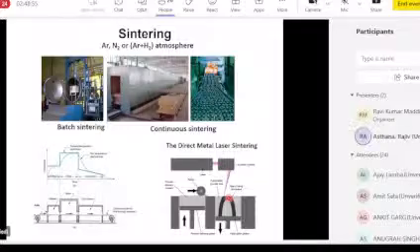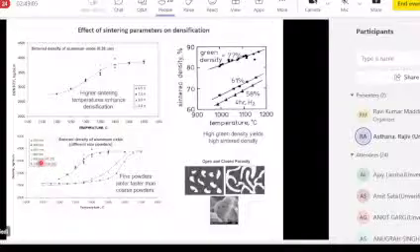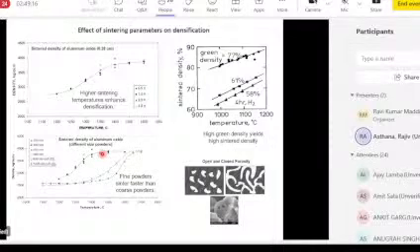Or as a function of sintering temperatures. Typically, higher temperatures give you faster densification and parts densify more. What is the effect of size of powders on densification? For a given sintering temperature, finer powders densify faster. You get better density with fine powders just because fine powders have a higher surface to volume ratio. So there is more sintering possible because of contact regions.